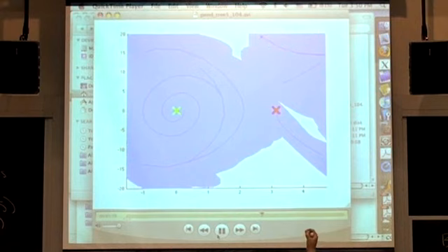If, however, it's execution time, I say the robot's got to run from here. I pick a point, it's already in the basin of attraction, and I just execute that trajectory. I think what you're alluding to is that it's in the basin of attraction of multiple trajectories, then I pick the one with the lowest cost to go, because those are all estimates of the cost to go that are centered around that trajectory. Okay?